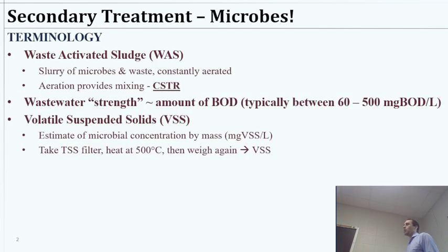So really, it's all about the microbes. We need to control them, use them. They're going to eat stuff. This waste-activated sludge is kind of our generic name for, I guess, the stuff during that process. Sometimes we might also call it mixed liquor suspended solids. That's one of the terms we'll talk about. But like a mixed liquor, meaning it's a mixture with different stuff in it, the bacteria and other things.